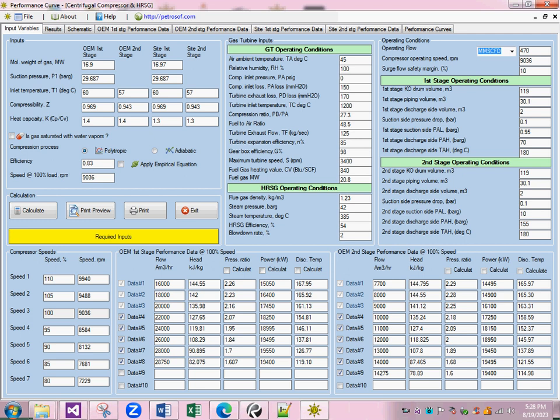For that one performance curve of 100% speed, the user needs to get this information from the vendor's manual, which is mostly provided along with the vendor's manufacturing data or the OEM manual. Here the user needs to provide 10 dataset values for each of these basic parameters in the respective fields in order to run the application efficiently and predict the site-based condition further on.